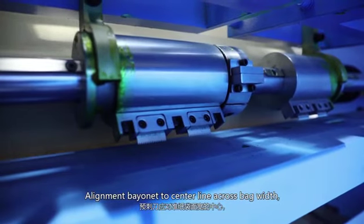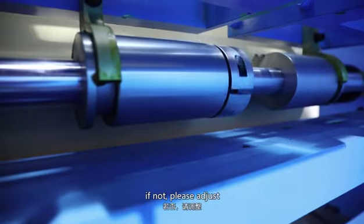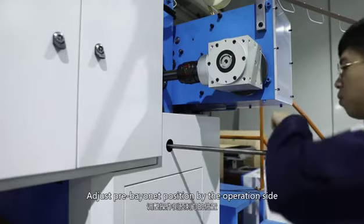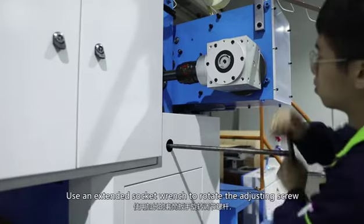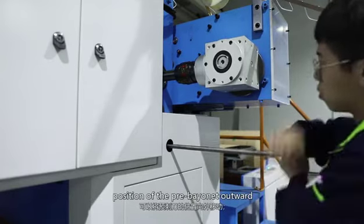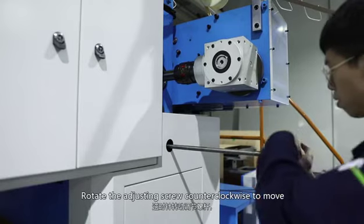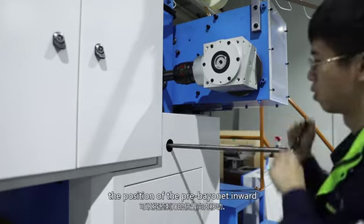Adjust the pre-bayonet position. Align the bayonet to the center line across the back width. If not, please adjust. Adjust the pre-bayonet position by the operation side. Use an extended socket wrench to rotate the adjusting screw. Rotate the adjusting screw clockwise to move the position of the pre-bayonet outward. Rotate the adjusting screw counterclockwise to move the position of the pre-bayonet inward.